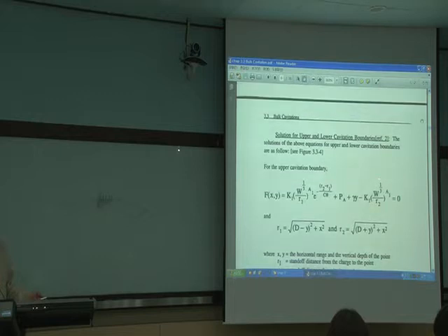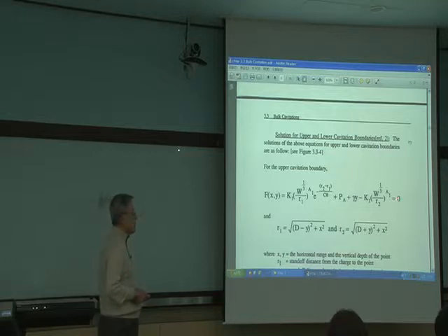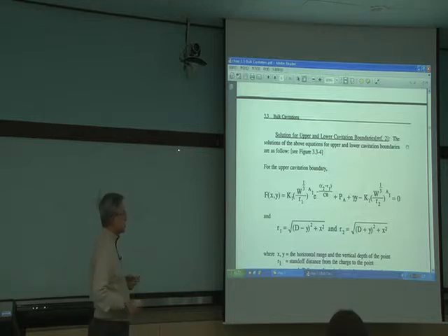So by looking at this, if this has to be equal to 0 or below 0, if it goes down below 0, you know, the water cannot sustain the tension, so you have to reset it to equal 0. So if it's not 0, if this is positive, that point is not in the cavitation zone. So then you have to move to the next point and check it out and all that. Okay.